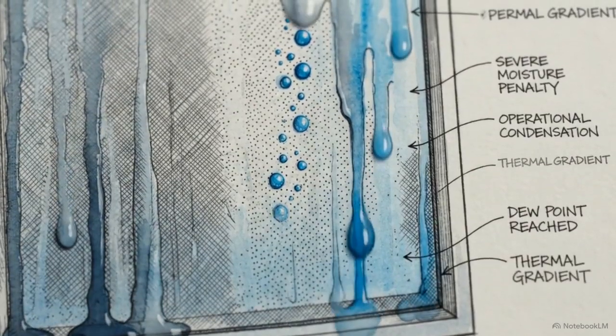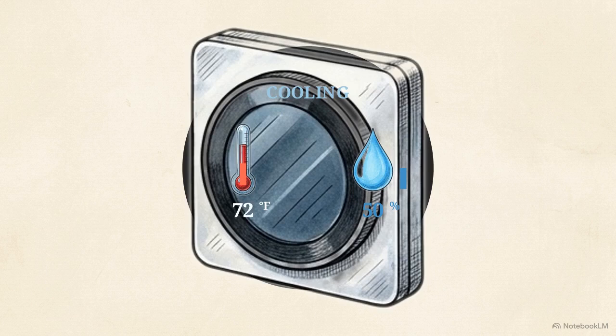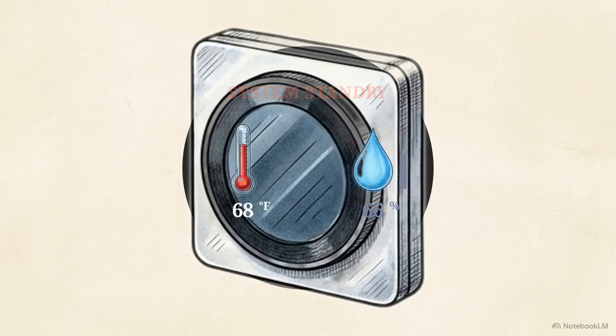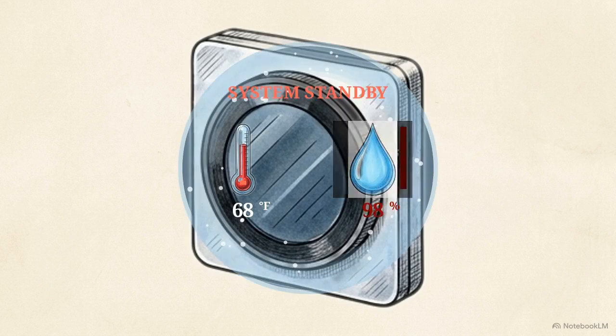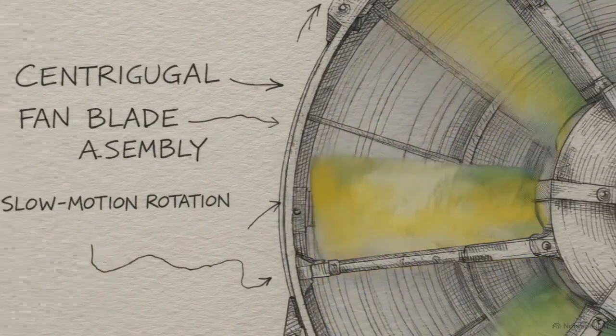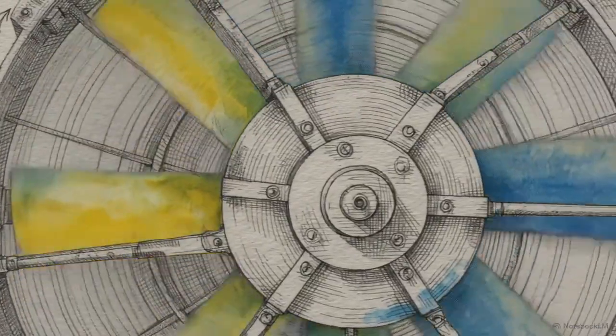Overestimating the capacity carries severe operational consequences. A system with excess capacity cools the sensible heat too quickly. The thermostat shuts the unit off before it has time to ride down the vertical axis and extract the latent moisture, resulting in a cold, damp building. HVAC design requires calculating the room's heat and determining the penalty of the ventilation code, and then mapping that entire complex thermodynamic journey to precisely match the exact capacity of the central plant.